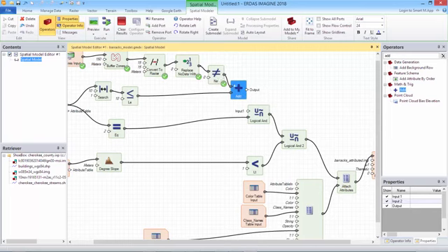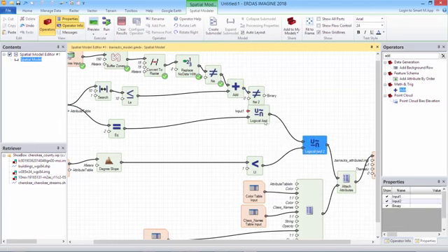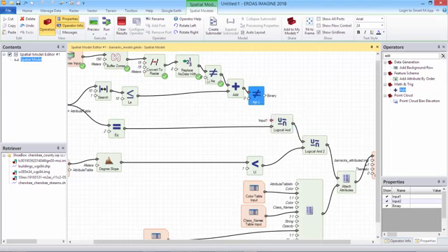So we can turn that back into a binary. Let's actually select our not equals, make a Control-C, Control-V to make a copy of it, connect that up to what we currently have there. Again, I'm going to just shift these out of the way a bit. So now we've done a not equals 0 again. So again, we're going to have that true or false situation.